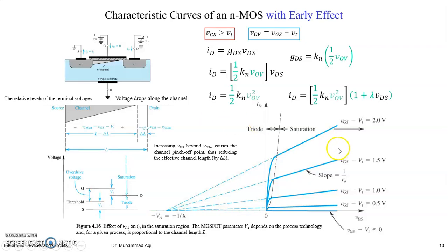How about PMOS? As I introduced in the previous slide, you would be having VSG here, right? VSG should be less than VTP, because for NMOS it would be VTN. VOV is what? So it is better to use a modulus sign here, to avoid the ambiguity in the signs and the opposite way of taking potentials. Instead of VGS as VSG and instead of VDS as VSD and so on, it would also be modulated. So you can do everything. You can check the book for PMOS for yourself, for all these things.